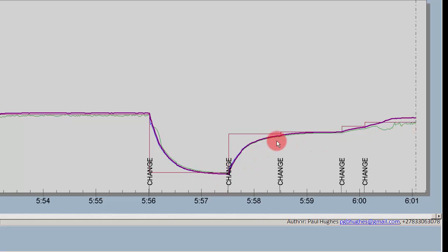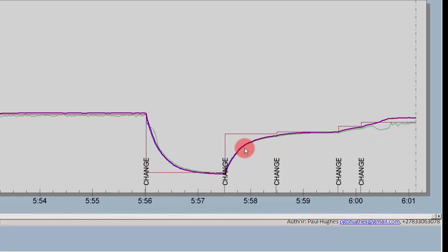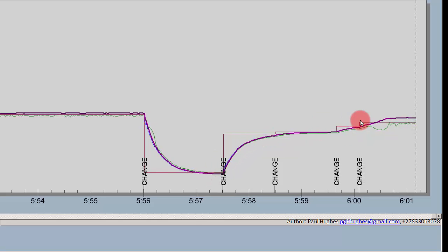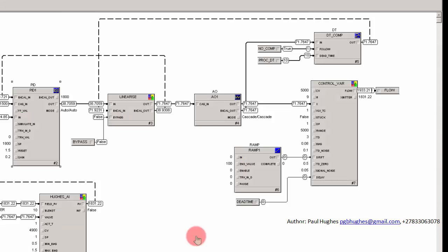So through the entire range of where the reading was unreliable, this fallback mechanism worked perfectly, and because we have this output linearizer, the feedback response has the same rise time throughout the entire operating range.